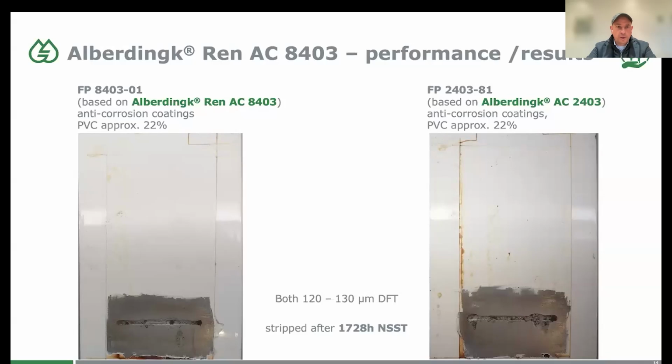So what I mean is, if you have these two phases, soft and hard, and the hard material's Tg is way above the testing temperature in your salt spray chamber, that will contribute to much better properties because you are having lower water absorption with the hot water or the hot salt solution.